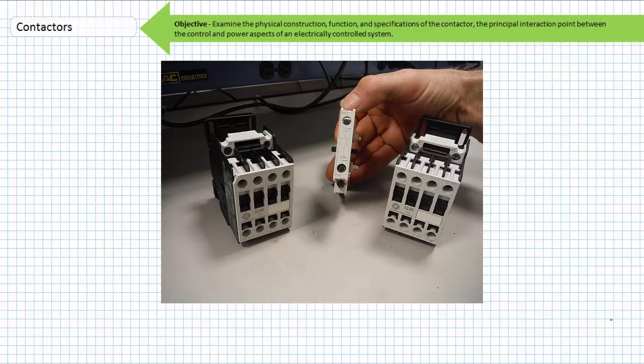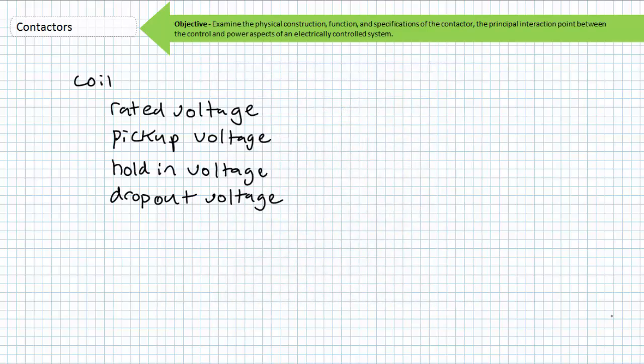Sometimes this is as simple as a plastic peg or lever, or complicated enough to require an additional interlock unit sandwiched between the contactors. When disassembled, we can see the levers on the interlock unit that slide into the ports on the side of the contactors on either side. Let us now discuss general specifications of coils and contactors and highlight some points of interest before we close up shop. The coil rated voltage must be matched to that of the control circuit voltage.